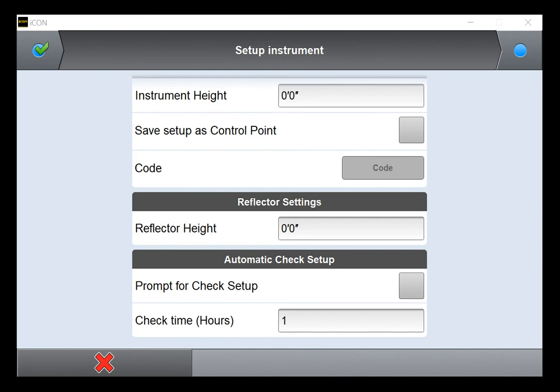It is important to choose your setup location wisely when you begin your day. Some factors to consider are volume of work in the area, so try to set up away from where people are working when possible. Movements of the building, so try to set away from the crane tiebacks, and try to set up near strong vertical members when possible, such as columns or shear walls. And location. Be sure that you can see your control points that you're going to use for your setup and as much of your layout area as possible to avoid large numbers of setups.